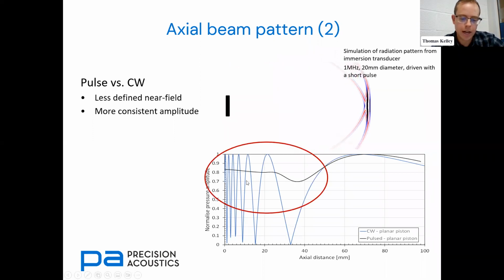So there's not really the same near field, far field distinction. This is related to the interaction, or lack of interaction, between the main plane wave and the diffracted waves from the edge of the transducer. But in summary, you can influence the field shape by your choice of drive regime. So that's the takeaway when considering designing a transducer here.